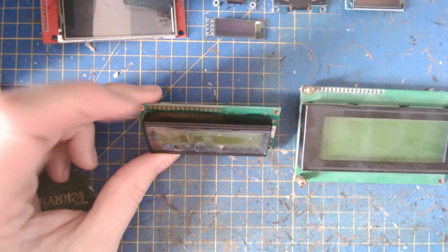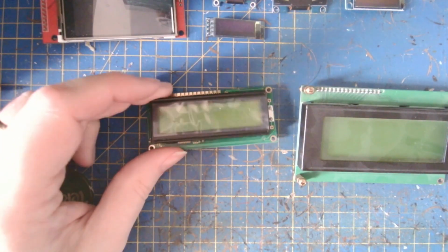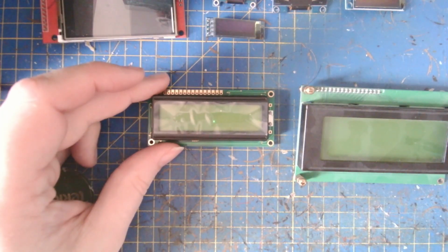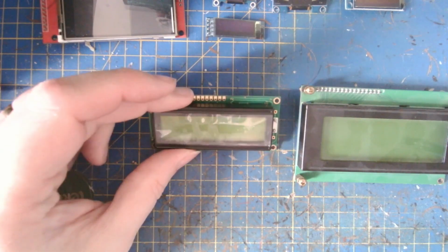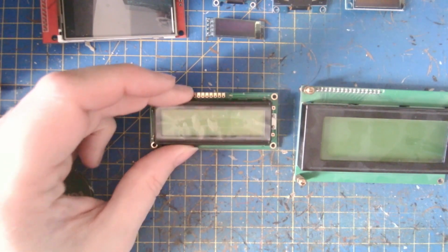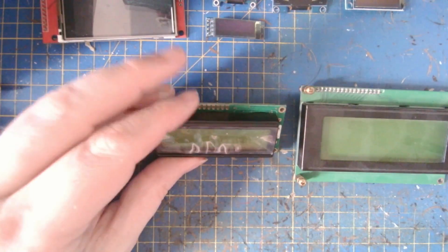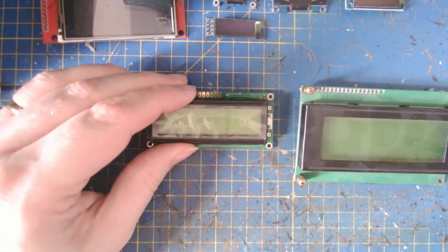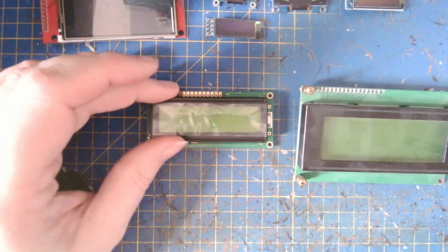You can drive them quickly using the parallel interface. Thing is, liquid crystal displays don't have a particularly good screen refresh rate. So yes, you can dump data to them fast, and there's a lot of tutorials online about driving these with Arduinos that use the 8-pin interface. And yeah, they work. They're clear, they're easy to read, they're low power, they're text only, or a very limited level of graphics. You can sort of do bar graphs with them.